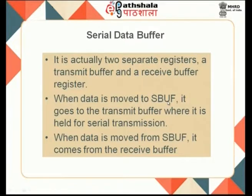Because of that particular purpose, the 8-bit data in 8051 is converted to serial information like 1 bit after 1 bit, and it will be sent or read through these particular port pins. Now this data has to be either reconstructed as 8 bits or delivered as single bit after single bit through a buffer. That particular buffer is called SBUF. So, this SBUF is used for supporting serial communication.